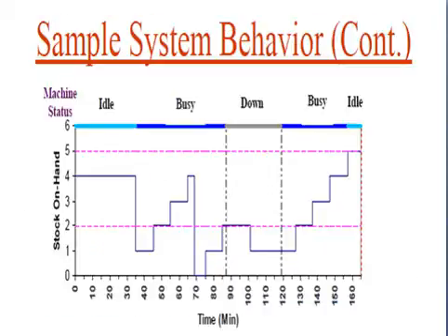So here, in order to calculate the machine busy time, that would be 87 minus 35, that's one portion, plus there is another portion also, 157 minus 119, and then you need to divide it by 165, and the value comes out to be 0.545.